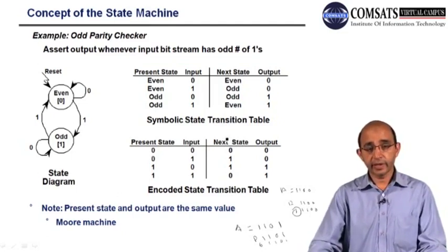So here we have to design a circuit that can check the odd parity, right? So the data stream, or the bit stream, had an odd number of ones. Here I've explained how we can make the number of ones odd. Here we already have an odd number of ones, so we place a 0 at the parity bit. Here we have an even number of ones, so in order to make them odd we will be placing a 1. So this is the parity bit, and now the number of ones is odd, right?